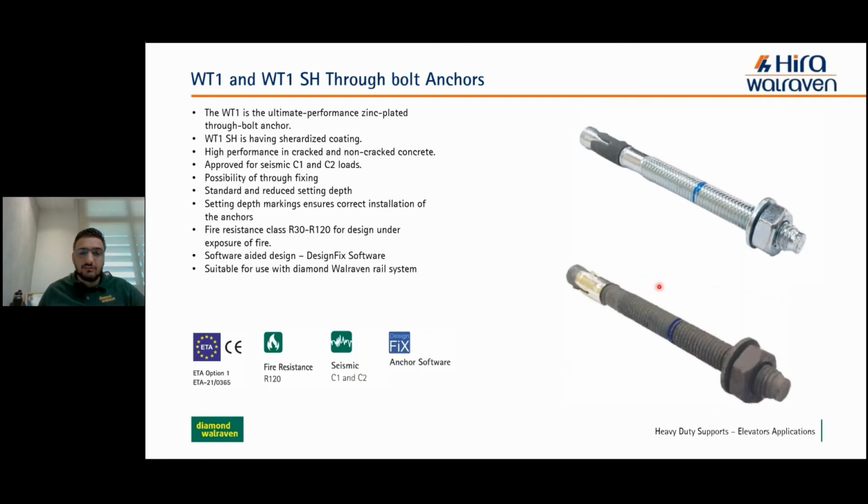What we can offer: we have the through bolts and the chemical anchors. Our recently launched new range of through bolts is called WT1 and WT1SH. WT1 is the Warraven through bolt, the ultimate performance zinc plated through bolt, while WT1SH has a Sherardized coating, which is better than hot dip galvanizing.